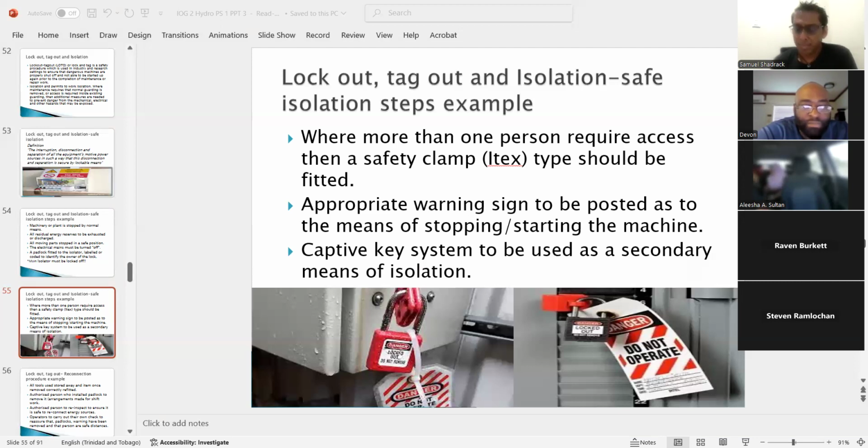Yeah, go ahead. If you put exactly what you said there, to ensure proper air quality, to ensure it's not flammable vapor, and sufficient oxygen to sustain life, that's nice. That's sufficient. But I know the rest of the students too, you should probably say 21% oxygen. Remember, going to a UK examiner, just try to get your mark, mention the oxygen concentration. Of course, you can mention hydrogen sulfide within certain limits. You understand what I did? I picked a reason from the heading.